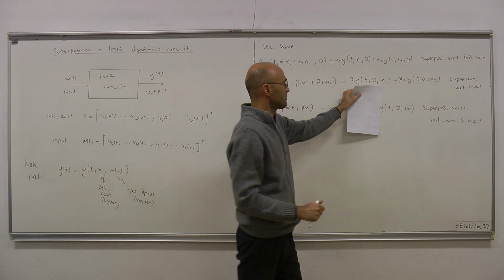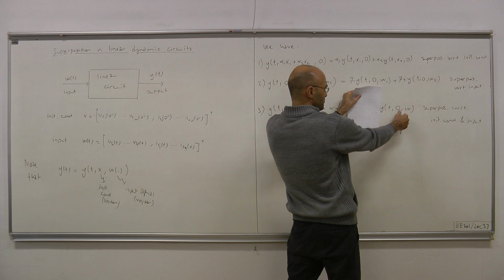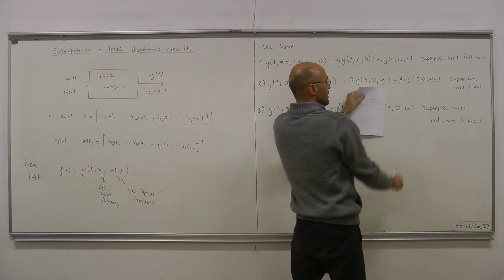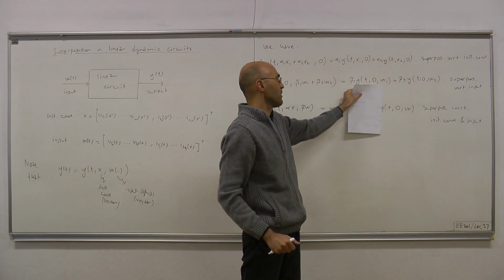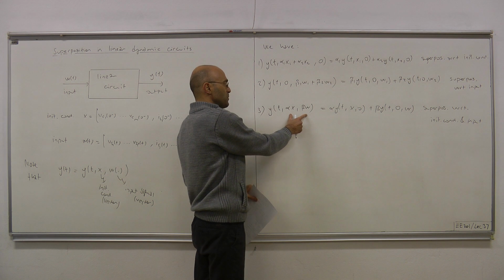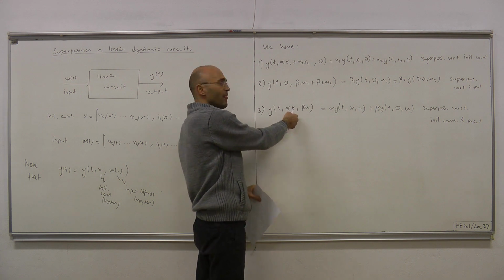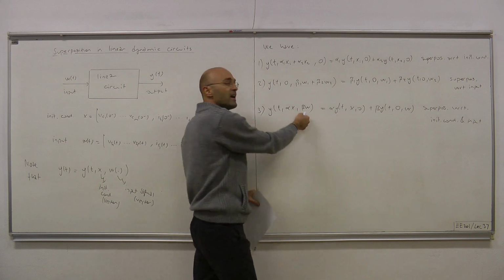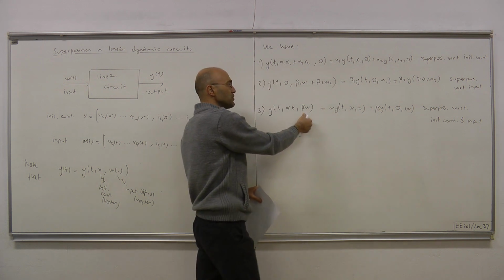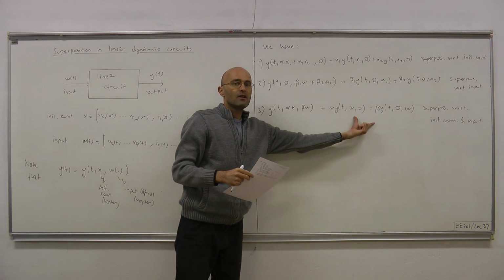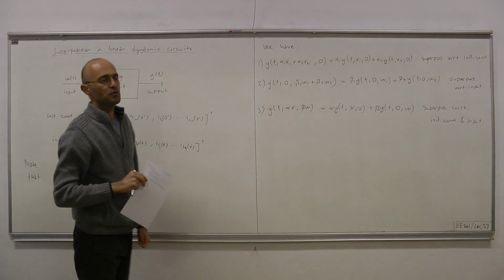And in the second case, you perform the zero state response, where you set the initial conditions to zero and you let only your sources be active. Then, in this third experiment, if you use a scaled version of the initial conditions that you use in the first experiment and a scaled version of the inputs that you use in the second experiment, then the overall response can be written as a linear combination of the first two responses.